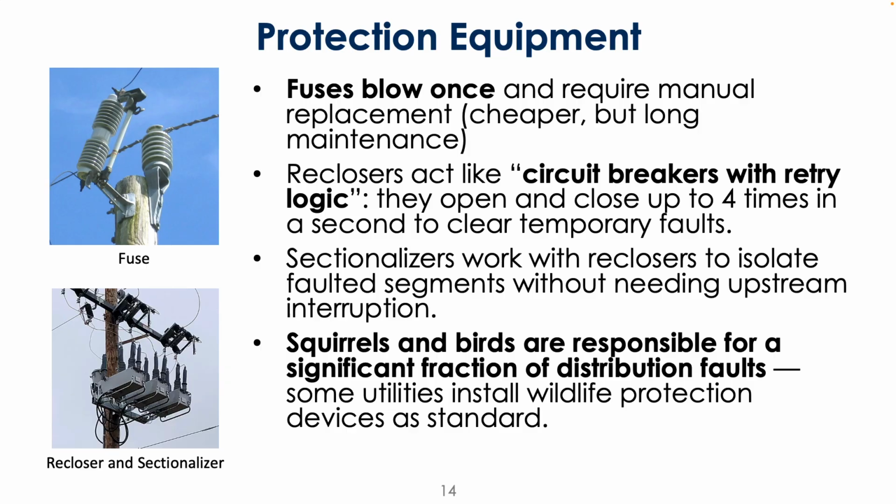If the tree hits the line and then falls over and is no longer touching the line, when the recloser closes the circuit again, everything is good, and it stays closed because you're not experiencing a surge in current. And so your fault has been cleared.